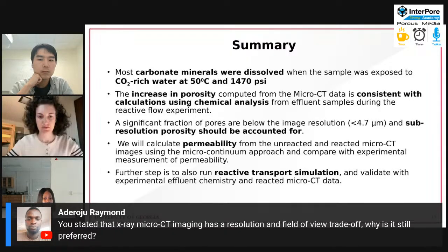And for X-ray micro-CT, you actually get a 3D representation of your volume. Yes, with SEM, you do get higher resolution imaging most of the time, but we need to remember it's 2D. So X-ray micro-CT is still a very powerful tool because you do get a 3D, unadulterated representation of your porous media to do most of your modeling work on. So, yeah.